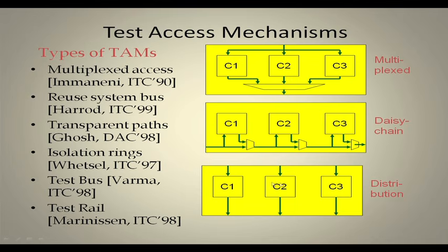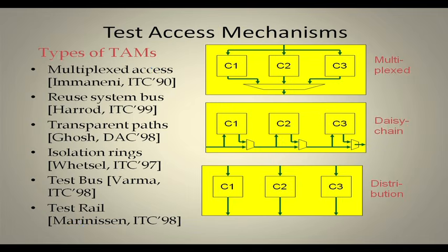the individual cores. So, the point is that here I can think of some parallel testing, like this C1, C2, C3, they can be tested in a serial fashion, they can be tested in a parallel fashion as well. Maybe C1, C2 are tested parallelly, C3 tested separately, or all C1, C2, C3 are tested parallelly. So, it depends, but of course, again the test bus is getting distributed, it is getting divided into the three parts. So, the width of individual test buses are going to be small.